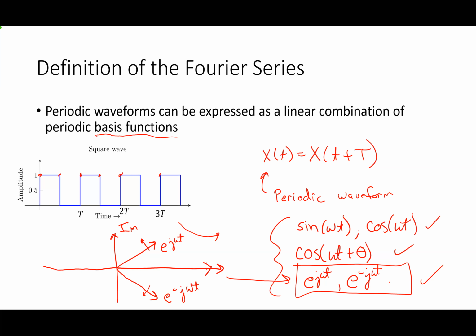And I know it's going to be twice as big because I'm adding the x component, which means the real component of the top vector and the bottom vector. So I'm going to get basically twice, right? That led us to this idea that cosine of omega t is always equal to 1/2 e to the j omega t plus 1/2 e to the minus j omega t. Two rotating vectors, one rotating forward, one rotating backward, that sum up to give me twice the size of cosine.